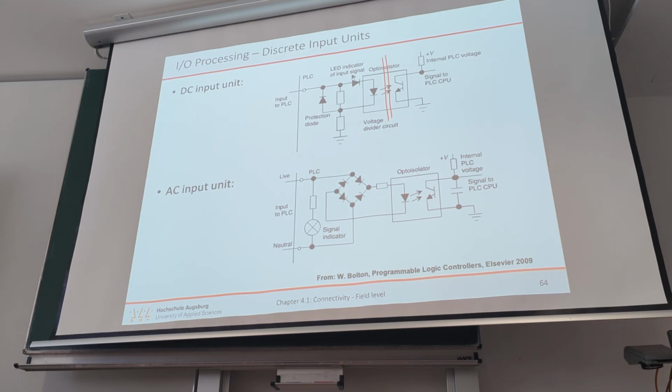So even if you would have very high voltage surges on the inputs, they won't directly affect the PLC because the PLC works in isolation, and usually only the channel is destroyed, and as the channel has some protection, it should be very robust even against noisy signals.